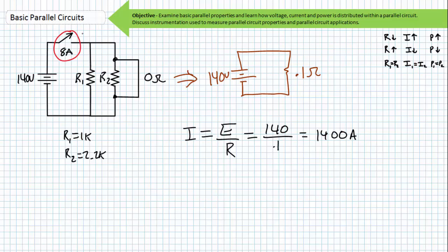In this case, a short, ordinarily associated with large current draw, precipitated an open, ordinarily associated with no current draw. And if you think about it, that's the point of the circuit breaker. It detected an abnormally large current draw and prevented it from burning down the house by opening the whole circuit. Good job, circuit breaker. Thanks for saving the day.